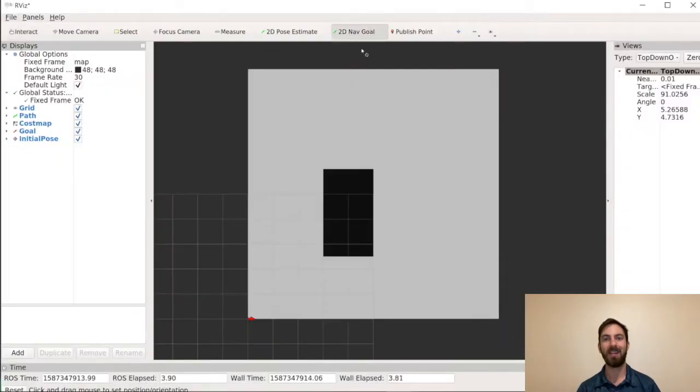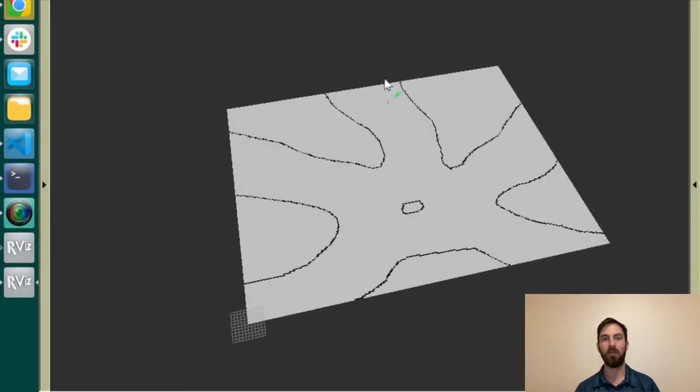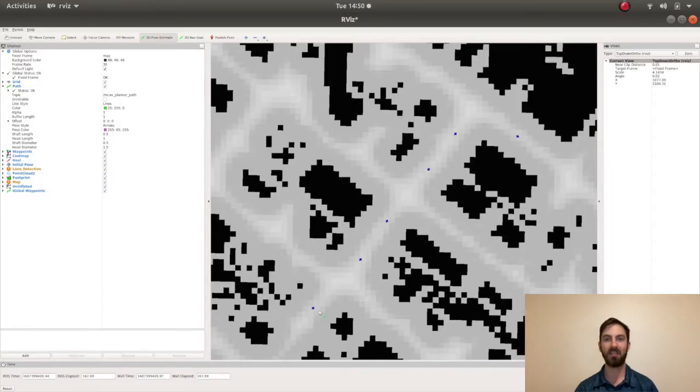The hybrid state A* algorithm is an extension to the widely used A* search algorithm, known for being efficient for finding the shortest path between points on a map. The hybrid state extension to this algorithm modifies it to better take into account the dynamics of the vehicle, particularly with regard to steering.